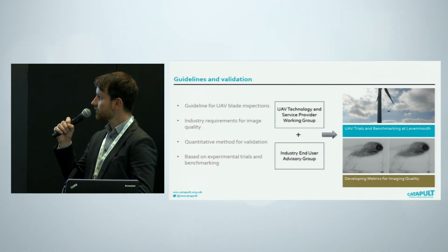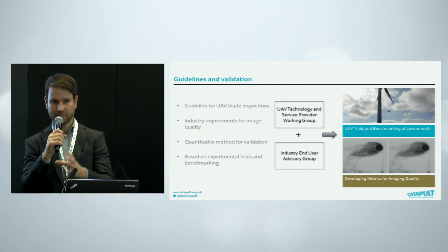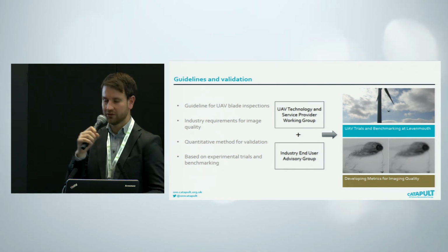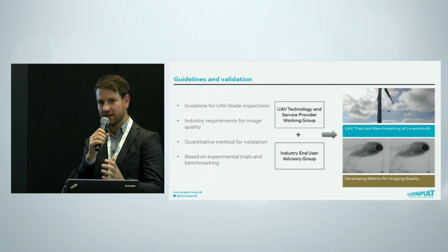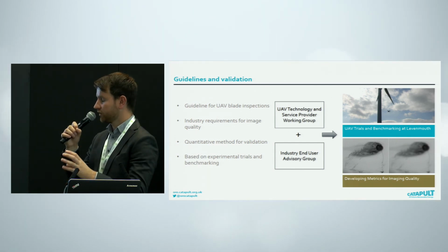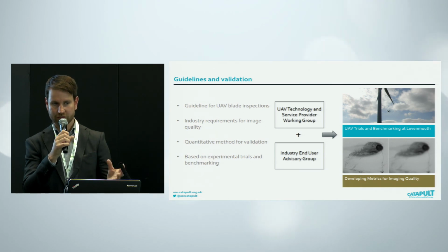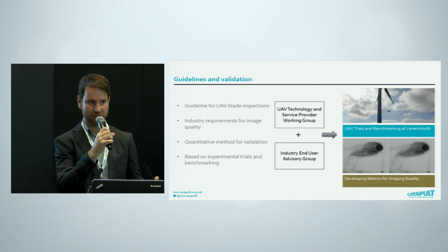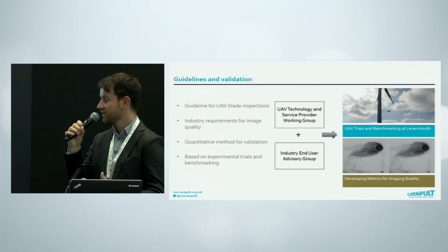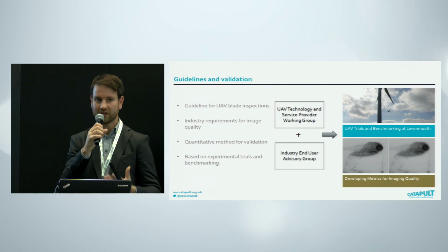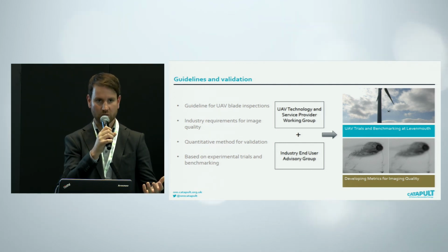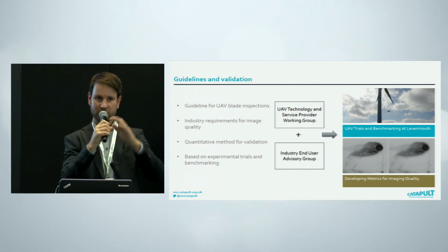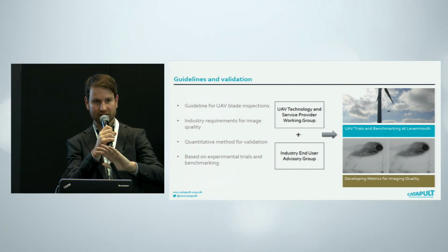So what we've done is we're using these drones to benchmark the defects on the asset. We've established a group of UAV technology and service providers who are going to come to the asset and take part in some trials. So we're going to run a number of trials of different UAV technologies, inspecting the turbines in different conditions, from different operational levels, different operational envelopes, different times. So, obviously you don't get all day to do inspections, so what's the difference in quality if you do it, say, in half an hour compared to 2 hours? What happens when there's plenty of cloud cover compared to a bright day, etc.